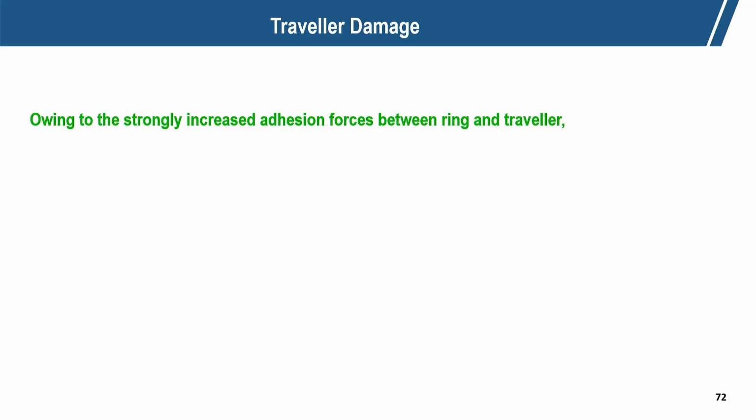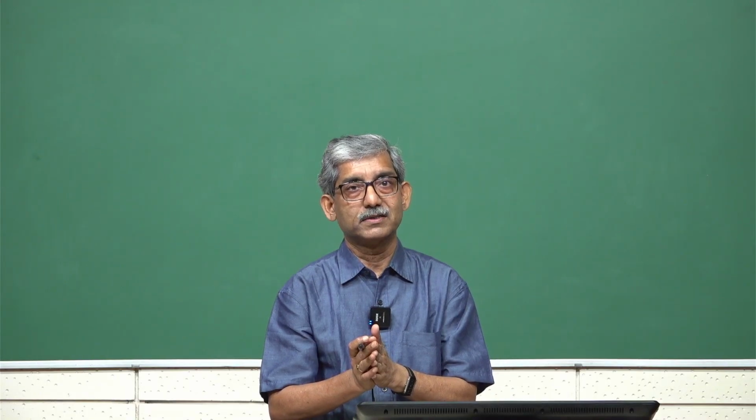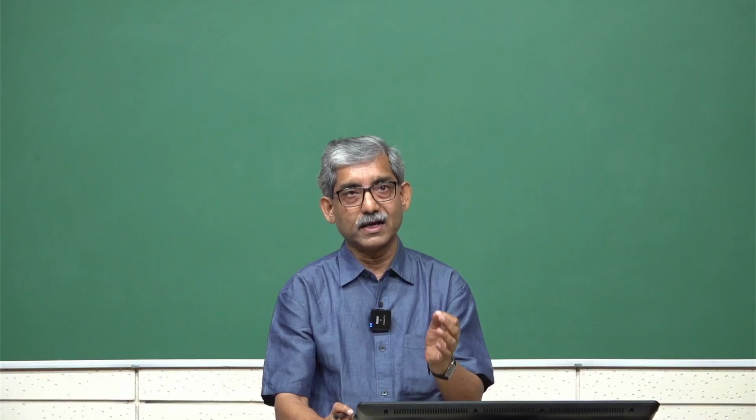With strongly increased adhesion between the ring and traveller, welding may sometimes take place. That means that at high pressure and high temperature, a welding action may take place.